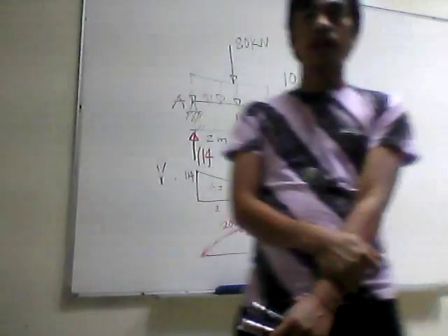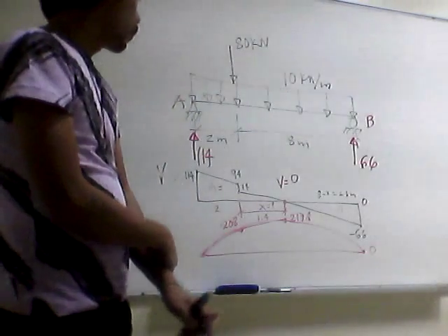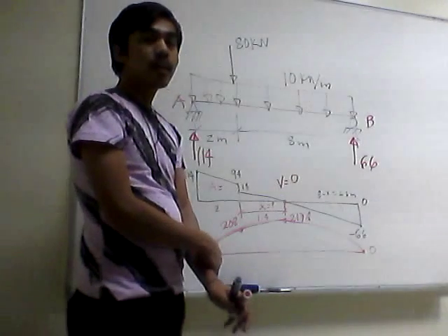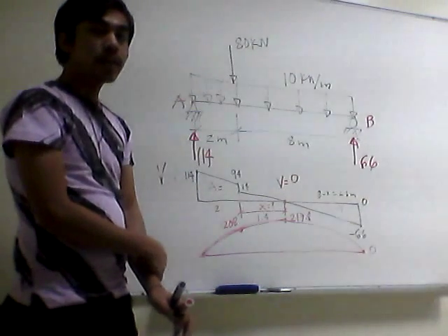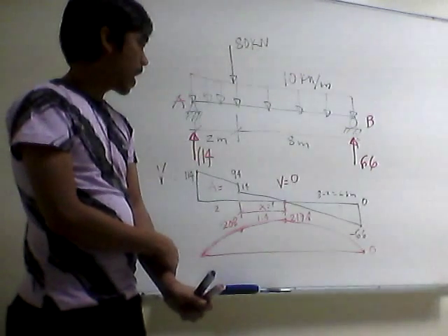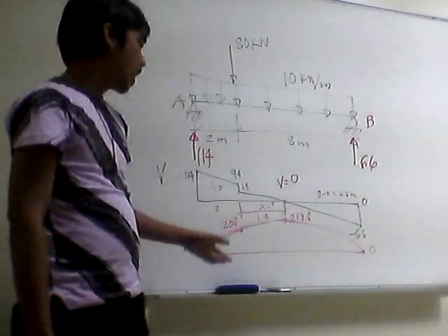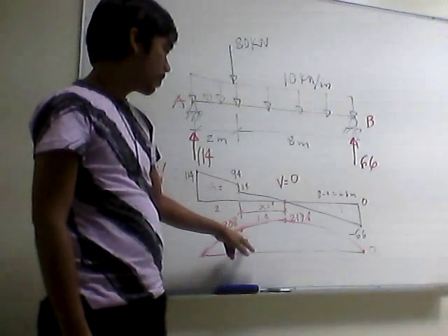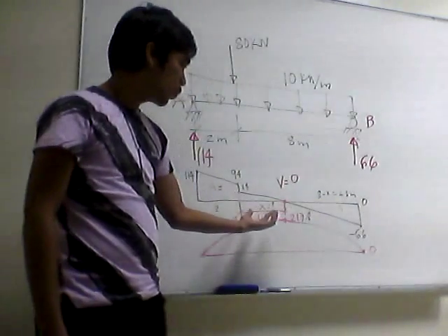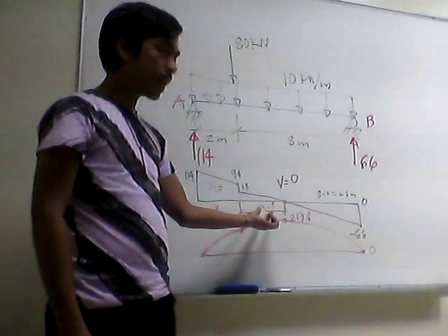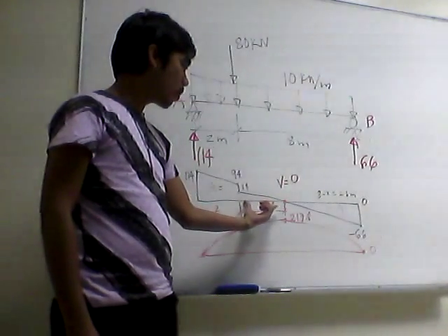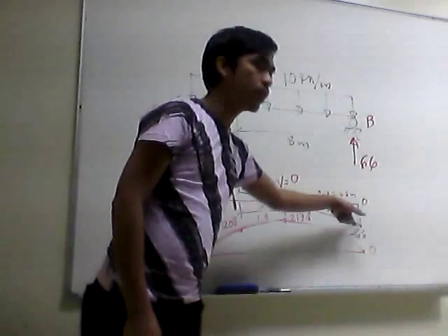Okay. So in this lecture, we learned one important thing to remember in drawing shear and moment diagrams later on. This thing is drawing the moment diagram when in the shear diagram we have to determine an unknown distance x, so that we can solve for the value of the moment along that portion of the beam.